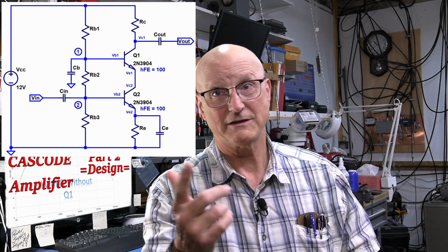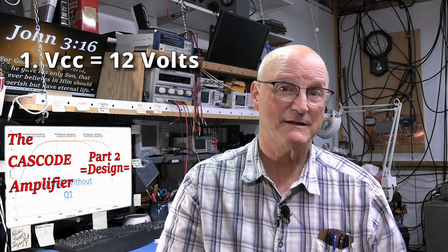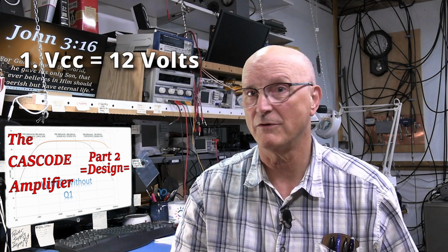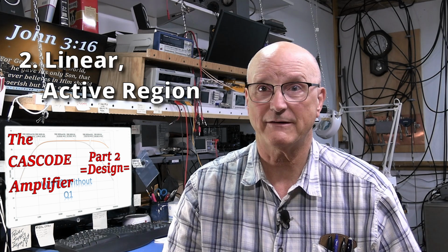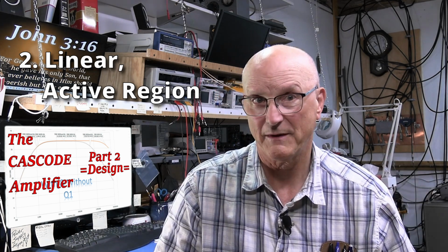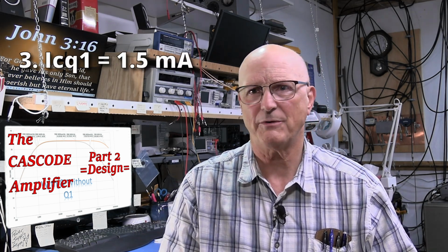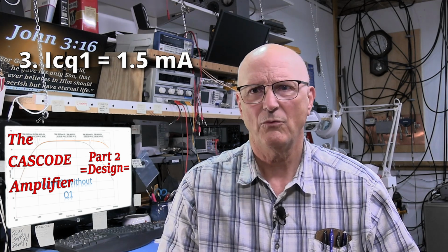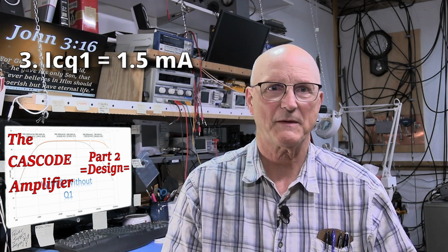So let's talk about this just for a moment. First, our power supply, or VCC, is going to be 12 volts. Second, both transistors are going to be operating in their linear active region. After all, we want a linear amplifier. Third, the quiescent collector current of the upper transistor, Q1, will be defined as 1.5 milliamps.